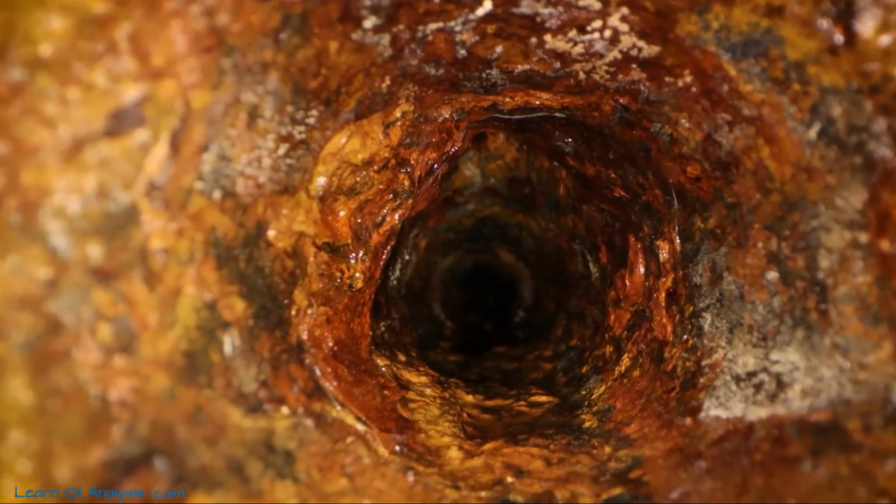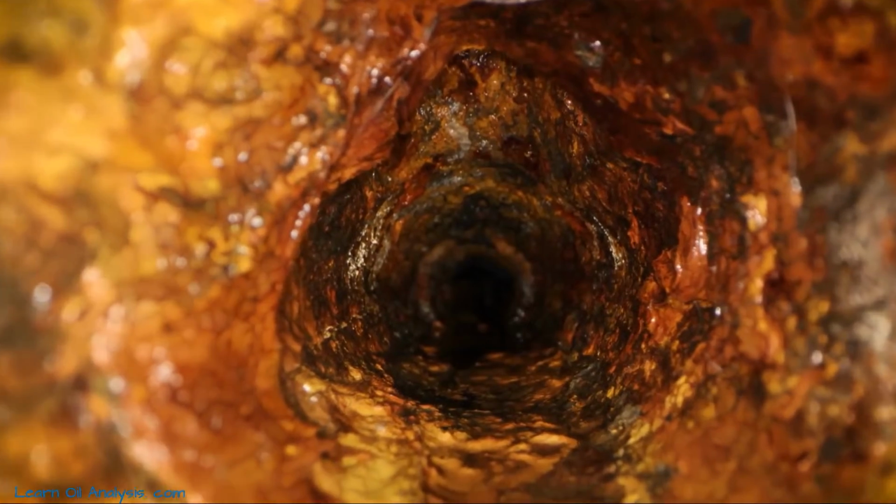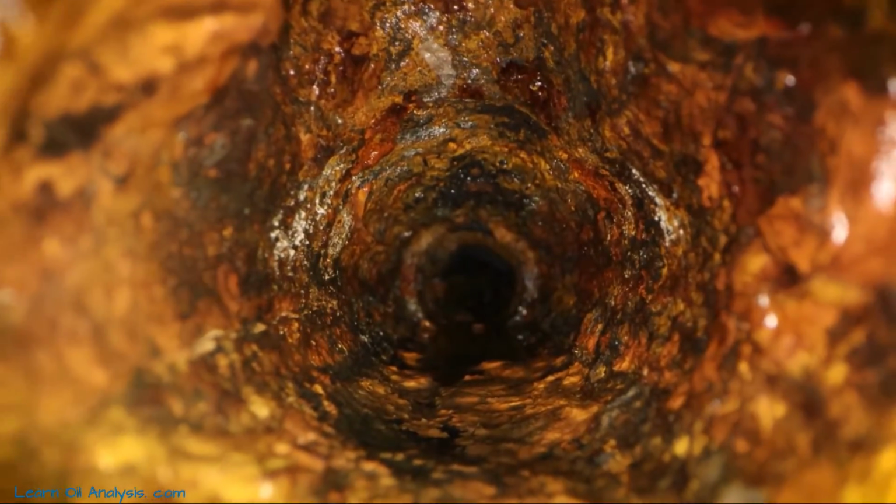On the other hand, the oxygen to nitrogen ratio helps us gauge the heating level within the transformer. Remember, I mentioned oxygen before. Well, the reason the oxygen can be relevant is oxygen is needed for oxidation to degrade the fluid or paper. A decrease in this ratio, meaning lower oxygen compared to its usual air composition, could suggest oxygen has been used up to oxidize the fluid or paper, usually by excessive heating.